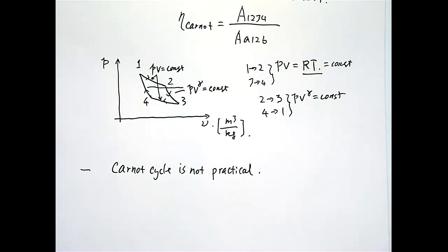So heat needs to be added in an isothermal way to the system, which, if you want to approach it, means you have to have the process happen very slowly. At every step, you add a tiny bit of heat from the outside, quickly convert that tiny bit of heat to a tiny bit of work, then reject a tiny bit of unused heat to the cold temperature reservoir, right? So the process must happen extremely slowly in order to approach the Carnot cycle.